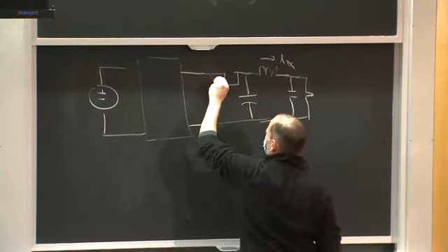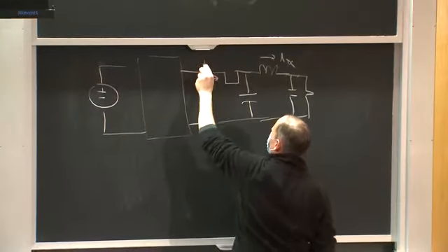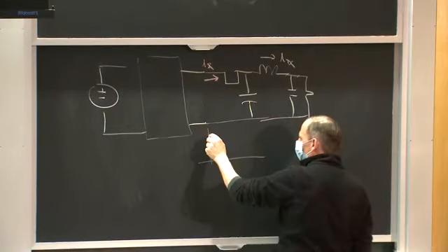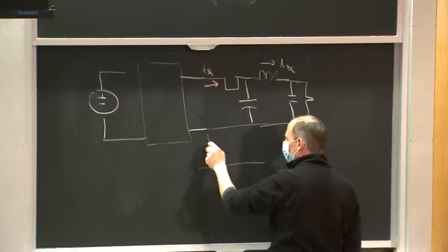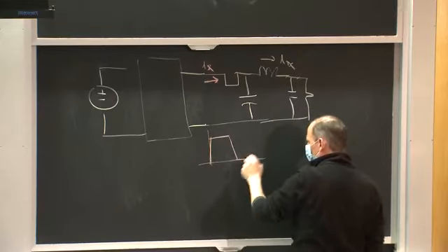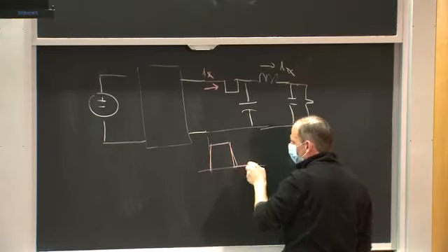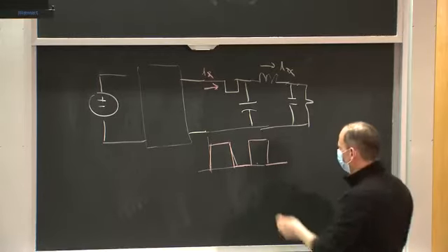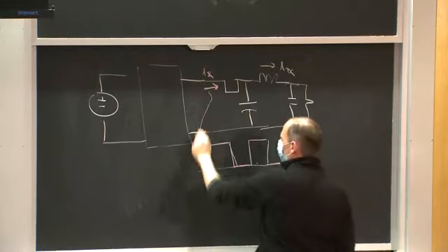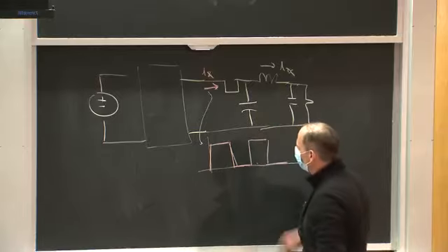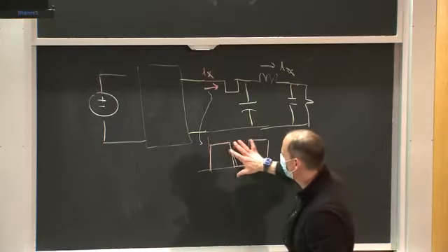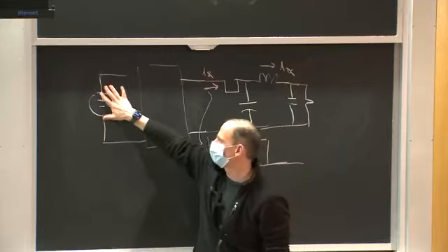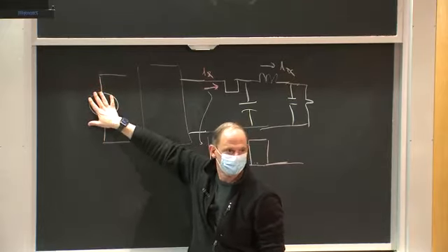If I were to look at this current that I'm drawing through the input switch, I'll call that IX, right, is more or less a square wave, right? It has some finite slope on it, but I'm looking at some kind of square wave slope with time. And so the frequency content is what drives my filter, and then that's what sets what shows up, say, at my input, okay?